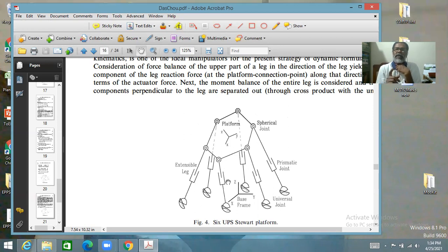Now here, parallel manipulators differ from serial manipulators, and their properties and applications are also different. Parallel manipulators typically are applied not for large sweeping motion, but for large forces to be supported, and motion is typically less, only in the spirit of adjustments. Small adjustments within a little domain, and it is the accuracy and force carrying capacity for which parallel manipulators are really known.